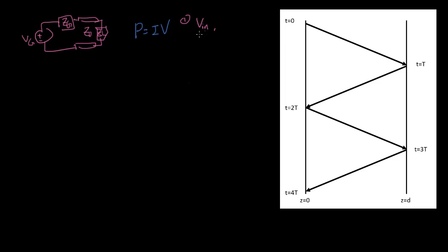So that's the input voltage, which is the voltage divider between VG divided between ZG and Z0, and also gamma G and gamma L, where Vn is the voltage divider between Z0 and ZG plus Z0, and gamma, I'll just combine gamma generator, gamma load is equal to new, which in this case is generator or load, minus old, which is the transmission line, over the sum of the two, so ZG or ZL plus Z0.